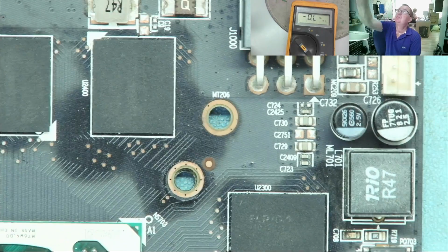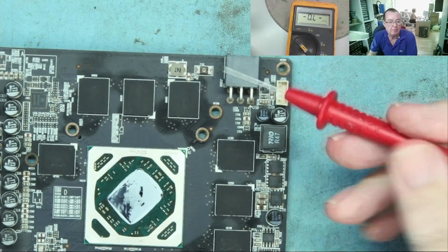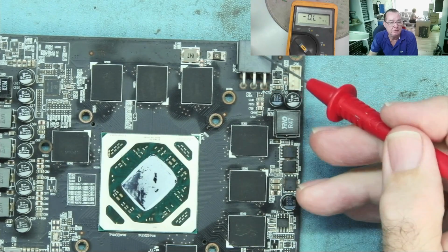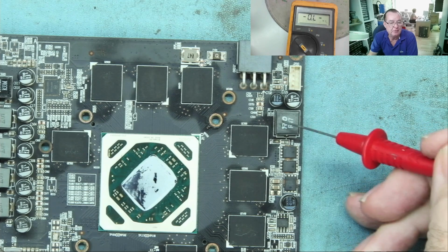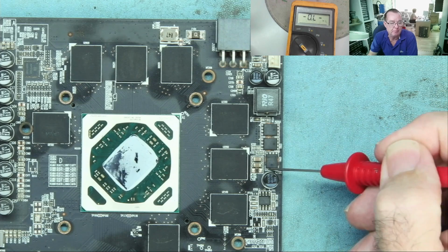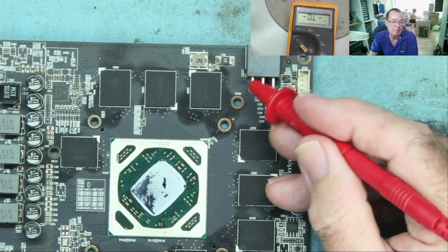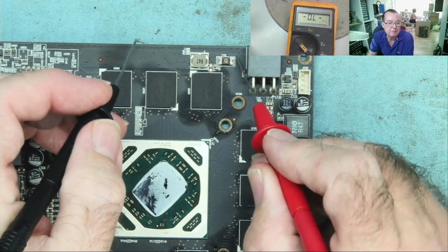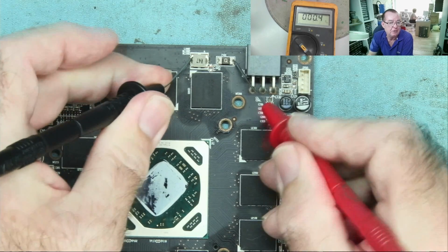How about these coils? Well, first off, this one and this one, because they're by the fuse and they're by here, are probably actually just filters. The way to normally tell is if there are any MOSFETs by them. Well, this has MOSFETs by it, so actually this probably isn't a filter. That one probably is a filter. We can check this. Go for the most obvious place from the fuse. Does it go to this coil? Yes, it goes to the coil.